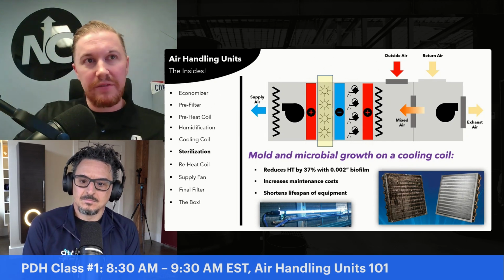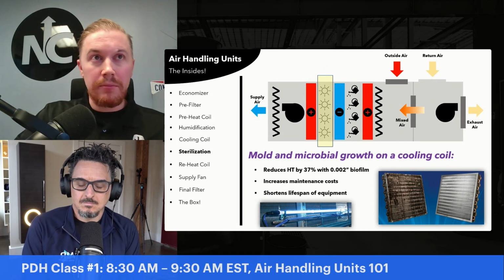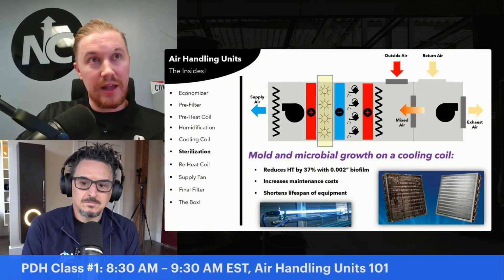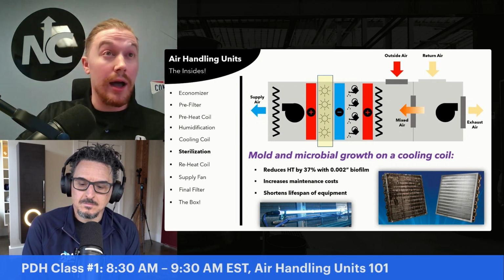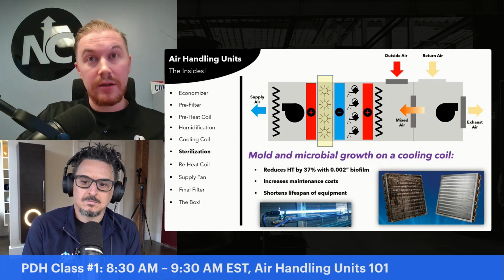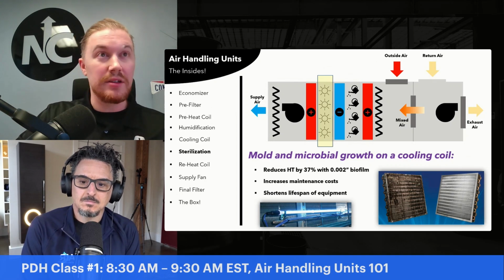the heat transfer significantly. The most important piece of this for everybody on this call, though, is never enter an air handling unit when these lights are on. There should be a kill switch when you enter an air handling unit that kills these lights, but these are UV-C, I believe, and those will burn your eyes and give you a tan you didn't want.